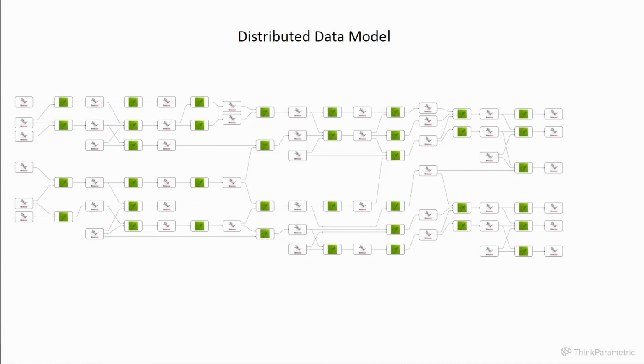The result is a network of models that each contain information about a specific part at a specific point in the process of the model generation. We call this a distributed data model. It consists of discrete sets of data that are stored in Rhino files and represented as attributed geometry. Each Grasshopper file in the network typically creates one type of object, and more specifically, one version of that object.